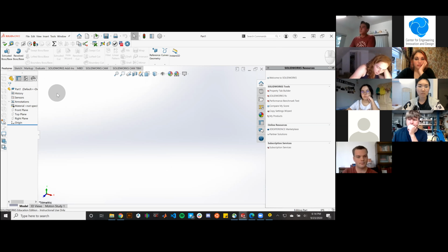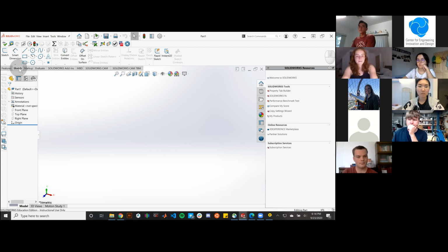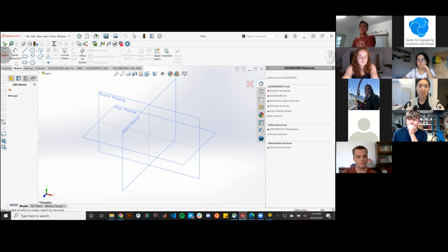So just to start us off, I think we're first going to create a new sketch. Up here on the left-hand side, you have Feature, Sketch, and all of these other tabs. Really, the things that we're going to be focusing on today are just Sketch and Features. So to create a new sketch, I'm going to click on the Sketch tab, and then click on Sketch. And anytime we create a new sketch, it's always going to ask us what flat surface we want to make a sketch on.